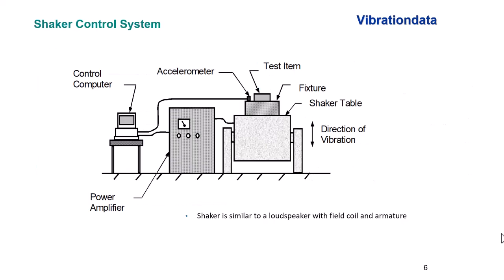SMC-S-016. Now here is just sort of a schematic about what a shaker test is, and we're going to talk mostly about random vibration and power spectral density tests right now, but later on we're going to be also talking about sine dwell and sine sweep. And if the shock level is fairly reasonably low, we can actually do shock testing on a shaker. Not very often, but sometimes. And if the shaker method can be used for shock testing, that's the way to go because that's the most repeatable of our shock test methods.